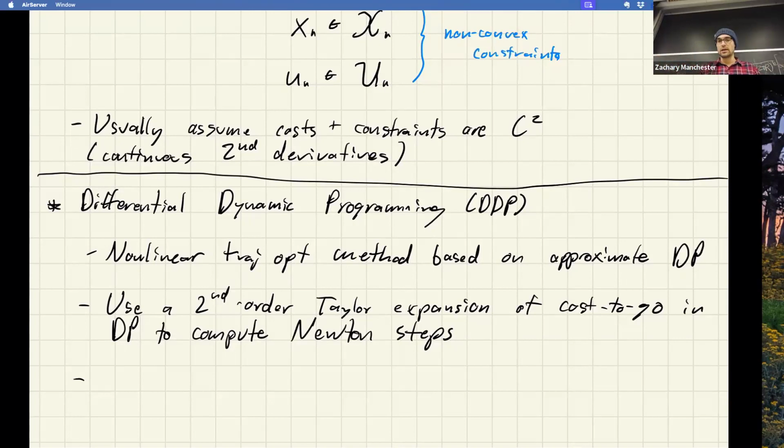And number two, they are what we call anytime dynamically feasible. That means that the iterates you get out of this always obey the dynamics. So you can basically stop early before it's fully converged and still run it on the robot and expect reasonable things to happen, which is not true of the direct or collocation methods. Those don't necessarily obey the constraints until they've fully converged. So for that reason, these tend to be popular for real-time MPC where you want to stop early.